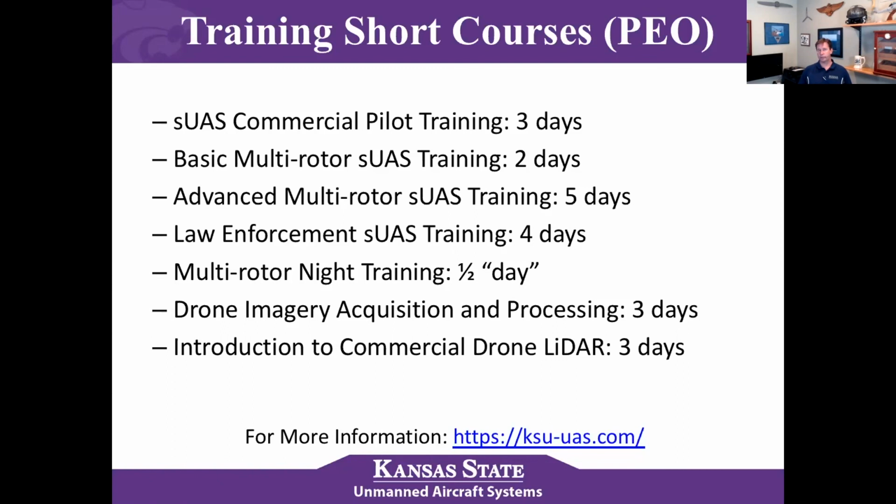Resolution or accuracy will change from system to system. That's why I say make sure you get data sets, control points, and accuracy studies. But from what I'm seeing overall with LiDAR data, PPK is much more accurate.